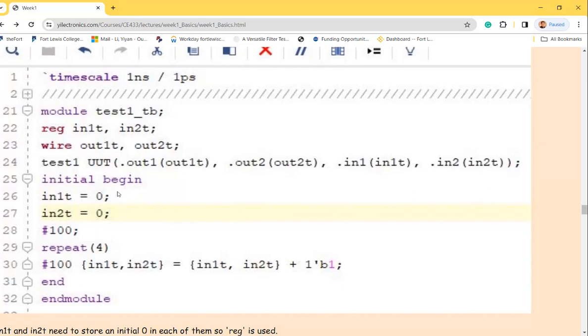And another thing you need to know is, in this parenthesis, the purpose is that you include that submodule into your test bench and you rename it. And immediately after that, you want to make a connection because your test bench has wires. You can think of it like this: if you want to connect to the oscilloscopes or power supply or the function generator, you need the wires and the connections. So that's how you do it here in Verilog.